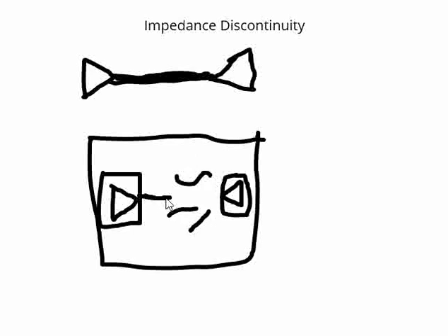So here we might have a fixed length and fixed width, and when we come nearer to these signals, we might reduce the width of this signal a bit, and again come back to the actual width that is required, whether it be 50 ohms or whatever.